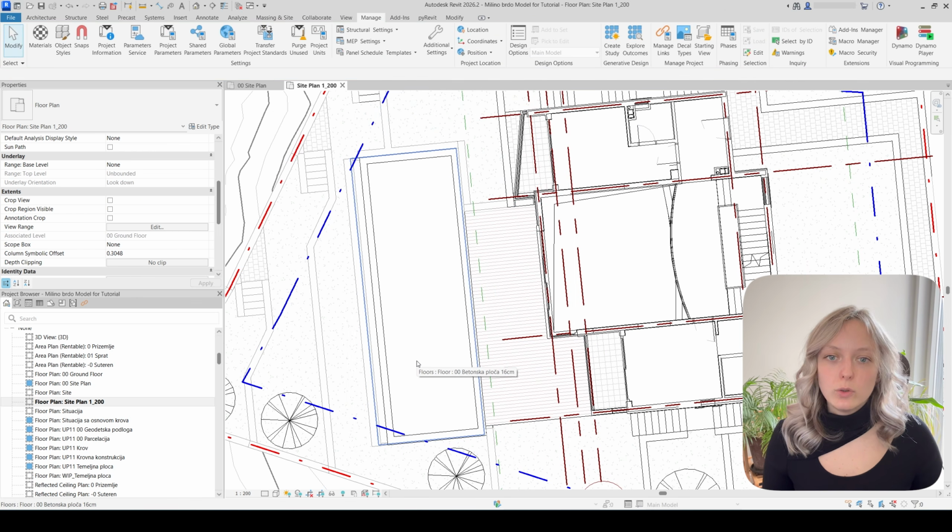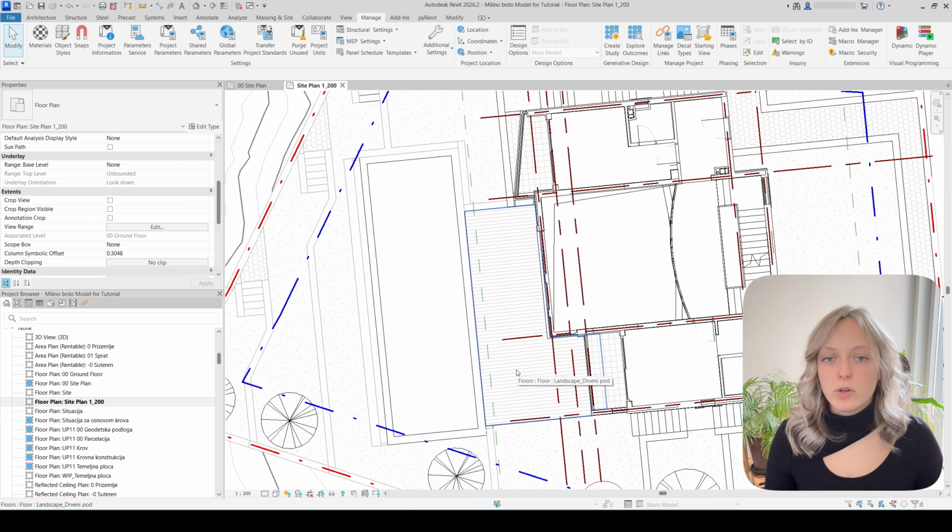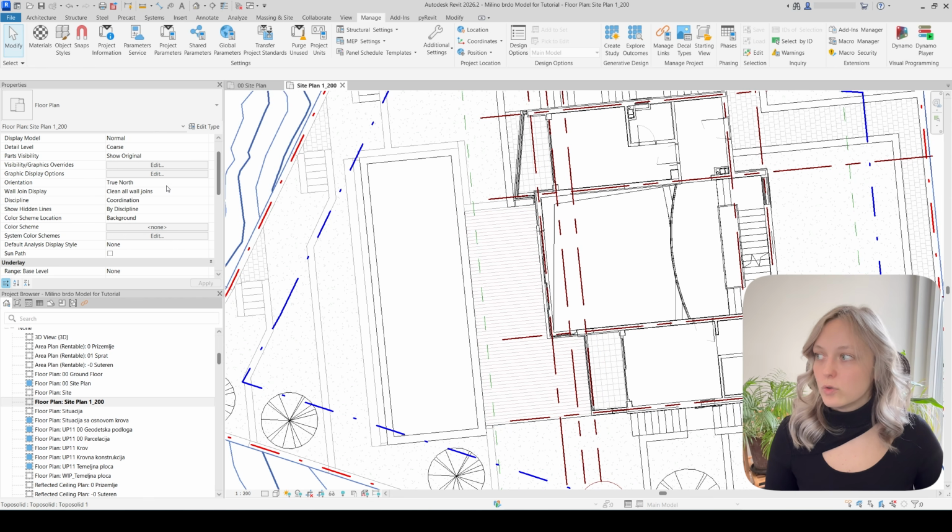Basically, I wanted to include this in the lesson because if you have drafting patterns, they will rotate badly when you change the orientation of your drawing. So if you want to have good rotation of the patterns, make sure that you use the model patterns. These will actually always keep the proper rotation no matter which rotation you choose here in the orientation part.